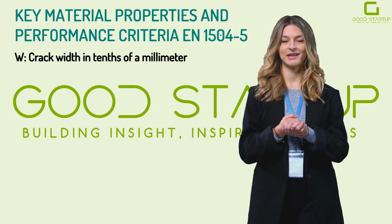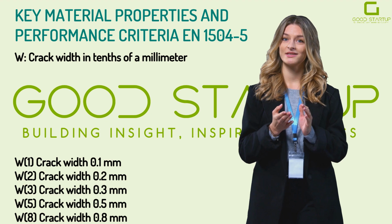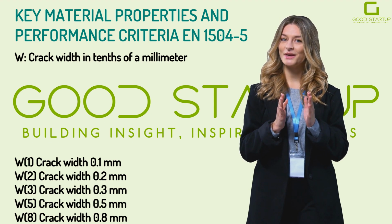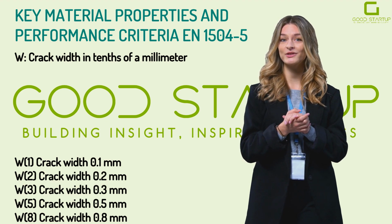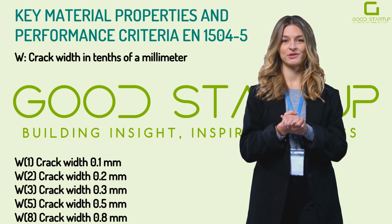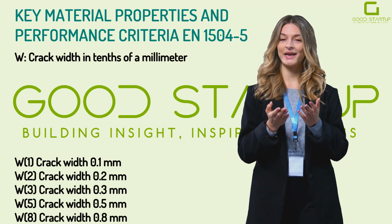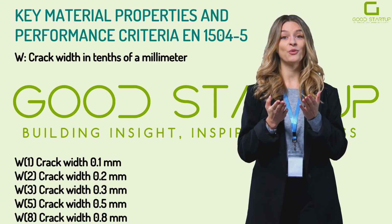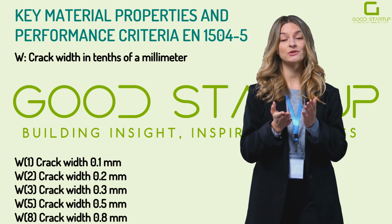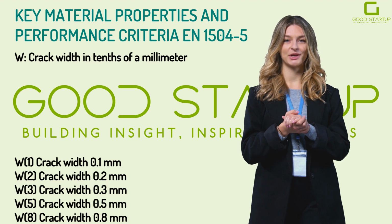Crack width penetration capability. Injection products are classified by the crack width range they can effectively fill. The standard uses a designation W1, W2, W3, etc., where the number is the crack width in tenths of millimeters that the product can penetrate. For example, W2 denotes a product suitable for 0.2 millimeter cracks, W5 for 0.5 millimeters, and so on. A lower number indicates a lower viscosity, more fluid resin capable of entering finer cracks. Engineers should ensure the chosen material's W rating matches the estimated crack widths. A high viscosity resin might not fill a hairline crack.